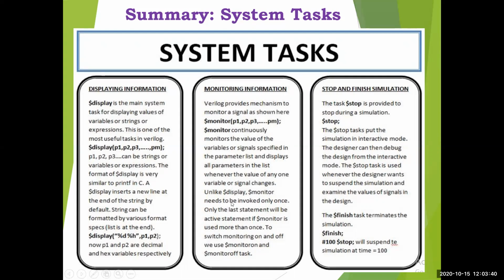Unlike $display, $monitor needs to be invoked only once. You need to write it only once. If you write multiple $monitor statements, the last one will overwrite the earlier ones. Only the last statement will be the active statement if $monitor is used more than once. To switch monitoring on and off, we have the $monitoron and $monitoroff special tasks.